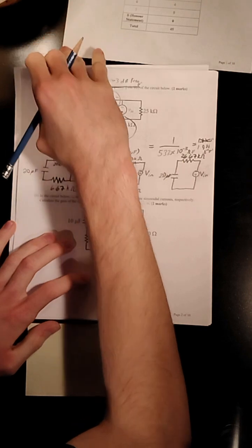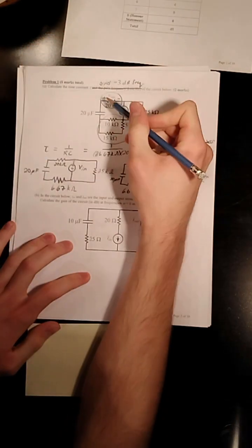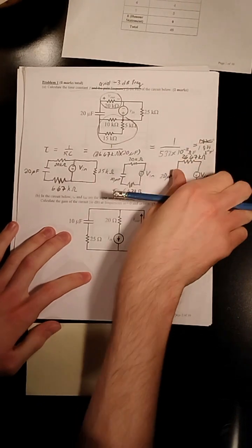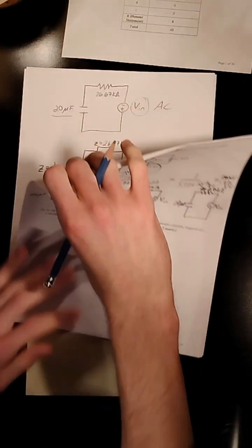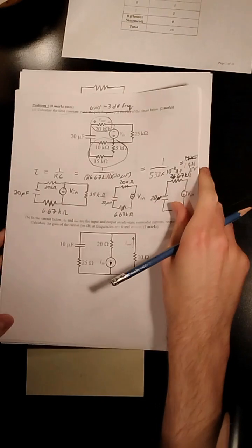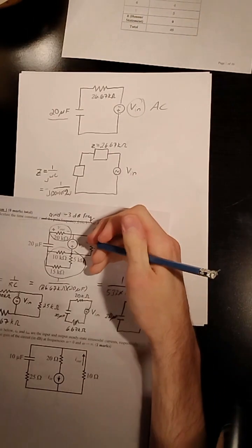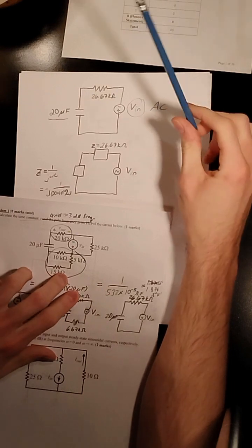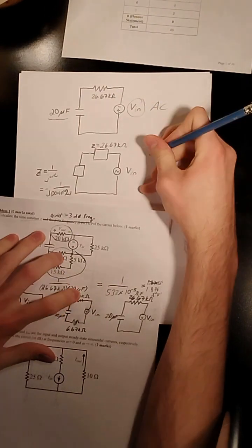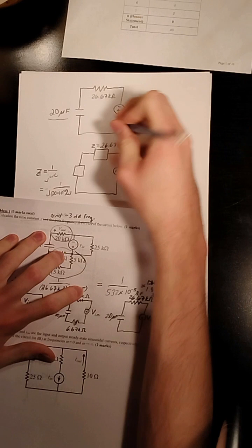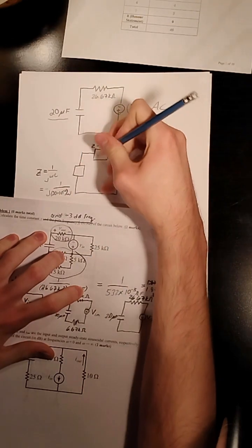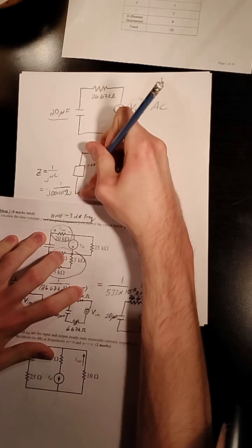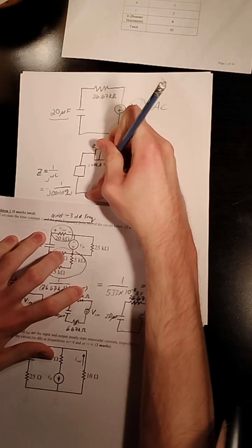So, when is V out equal to 1 over root 2 times V in? That's our question. So, you can see how, hopefully, we could divide this into a 6.67 kilo ohm and the 20 kilo ohm that we're worried about for the voltage drop.